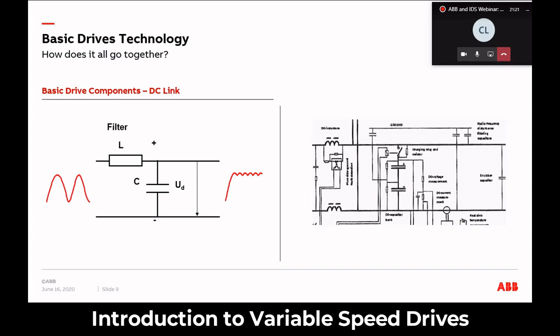And then as a result of going through the DC link, we now have a much smoother DC voltage. You can see initially we have that charging time because of the capacitors getting charged to the DC voltage point, and then from there we have a very constant voltage. Now on the right hand side you can see there's a little bit of ripple that I've applied.